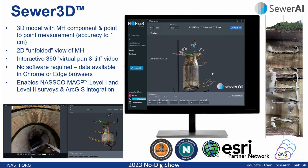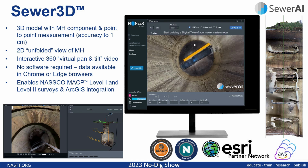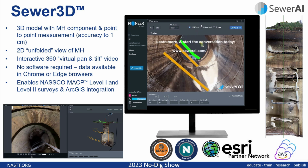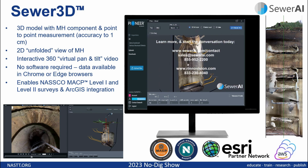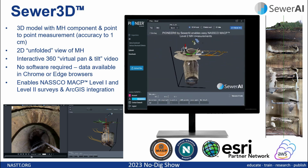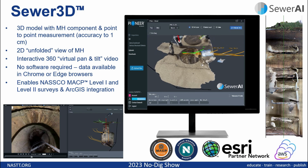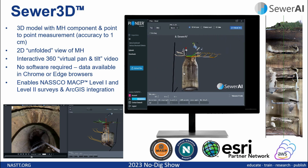The method used to render these 3D models is called photogrammetry. Photogrammetry is the use of advanced mathematics to calculate the position of digital pixels as points in 3D space. Inside the 3D model, one can quickly measure components in the structure, and conduct custom point-to-point measurements to an accuracy of 1 centimeter. There's also a 2D unfolded view of the structure, which can also enable vertical measurements and can be useful for identifying connecting pipes or missing bricks, etc.